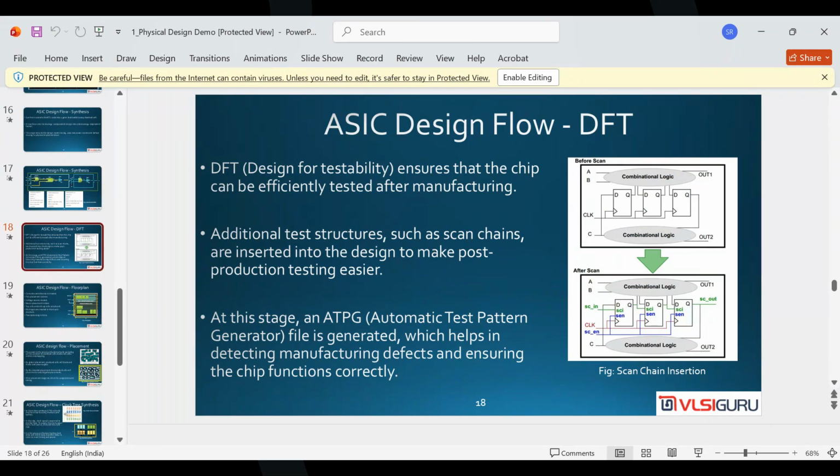See, once you have designed a chip, how are you going to check a design which has billions of transistors, in nanoscale? If there is some wire defect, which has wrong data in that particular net, how will you identify it? It's very difficult. You cannot dig down to find which net has the problem. That is the reason we insert DFT logic.